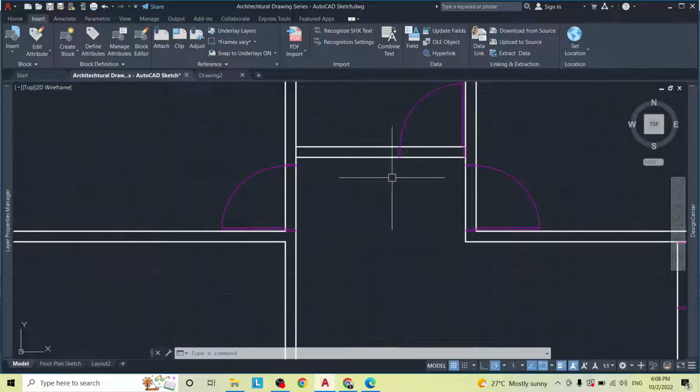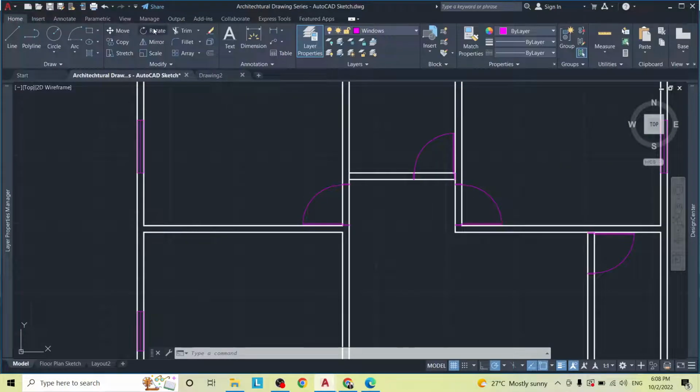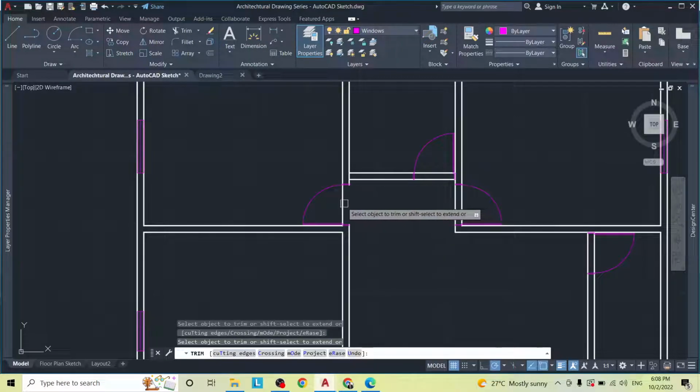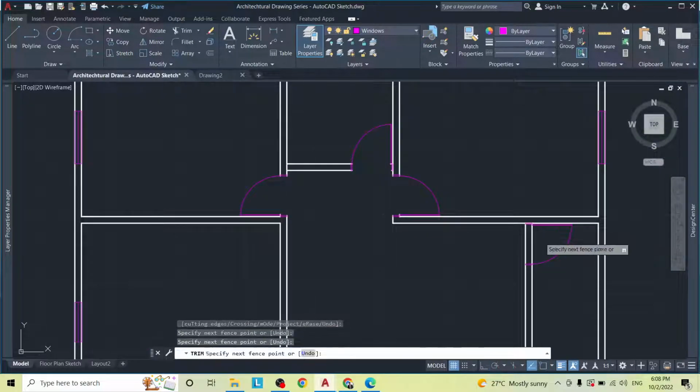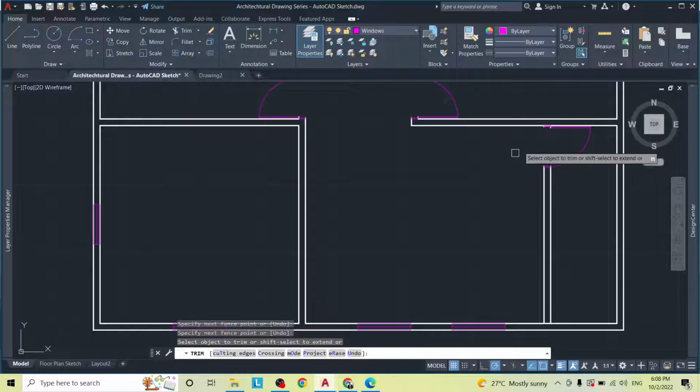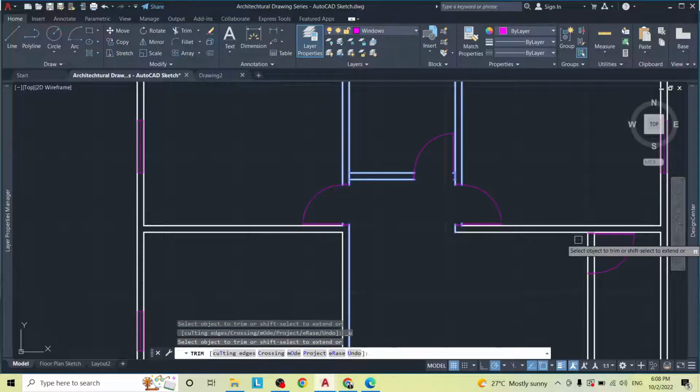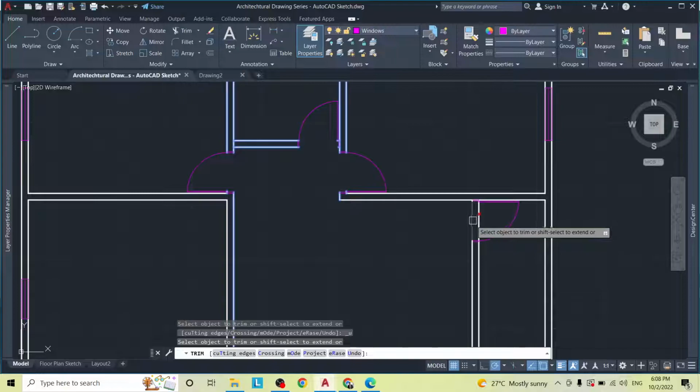Next step, we're going to trim away all of these entrances, okay? So let's go to the trim tool, trim. If you're using AutoCAD 2018, remember to right click first after selecting the trim tool. Otherwise, just click, click, click. Rather than click, click, you could just click once, select the entire area you want to trim out like that. Boom. I'm going to undo that because I only want one line trimmed away.